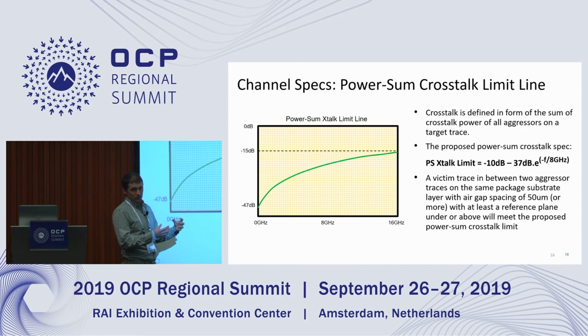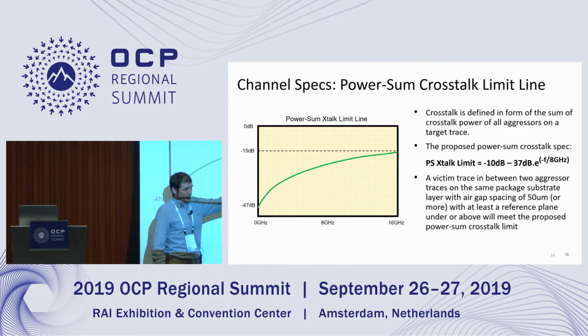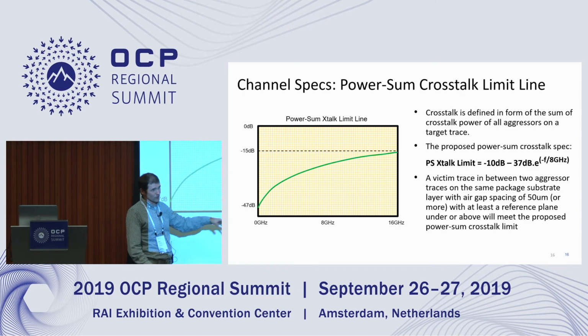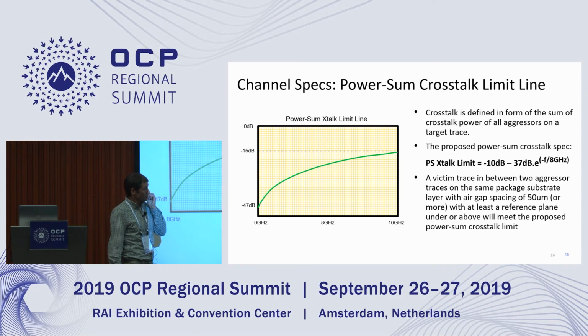And this is something that's generally achievable in a package substrate routing technology with something like 30 micron dielectric thickness and an air gap between the pairs of 50 microns. So it's not necessarily what's required for functionality, probably going up to 15 dB for functionality. 8 gigahertz would be fine, but this is what you would just get with typical routing and 130 micron bump pitch. So are you assuming a silicon spreader, or you're assuming a FR4 type of? Something like an FR4, yeah. 3.5 dielectric constant.